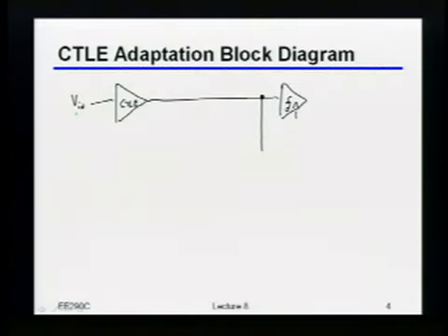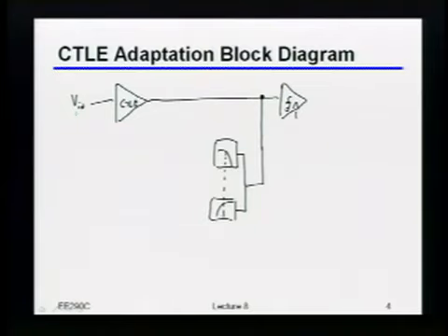Can I just put a filter? Yeah. Do I need one filter? Two. Two filters, right? So I basically do one low-pass filter and one high-pass filter. If I've done this right, then the cutoff frequencies of both of those filters should be the same, some half-point frequency. Now once I've done that, how do I decide which one has more energy? Or how do I compare the energies?